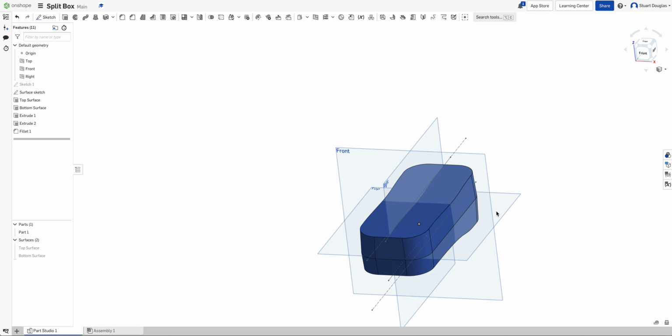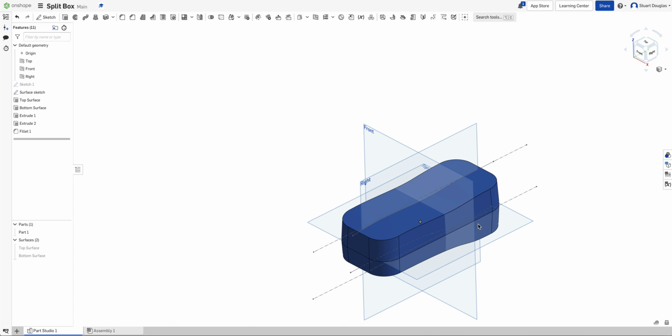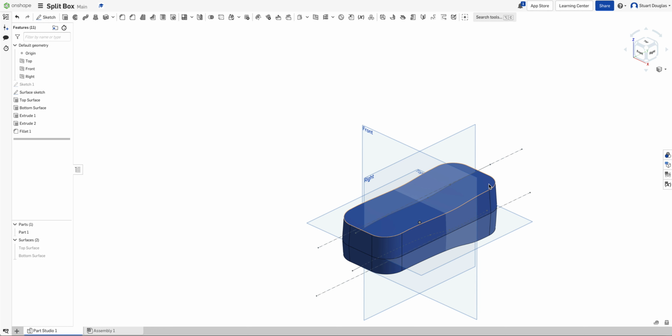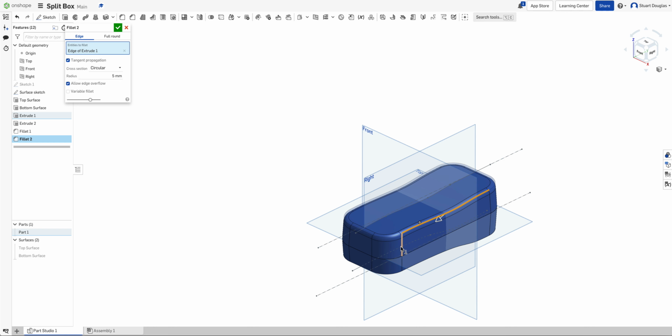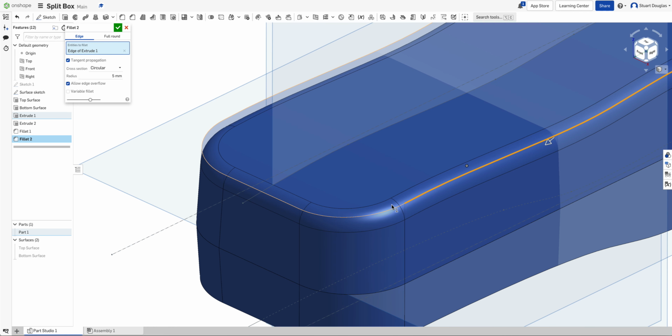So now we've got a round on those edges. And then we're going to add a round on the top edge. And because we've rounded the corners first, it should see this top edge as a linked edge. Just like that. In other words, as I round it, it tries to follow it all the way around because I've rounded or filleted these sides.